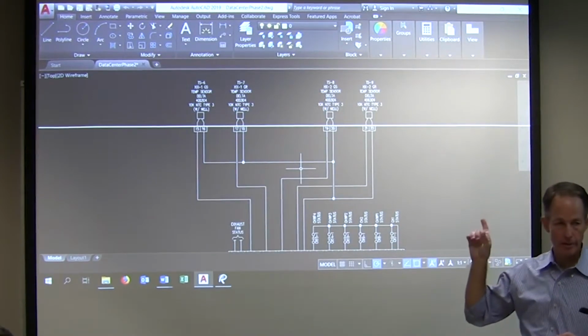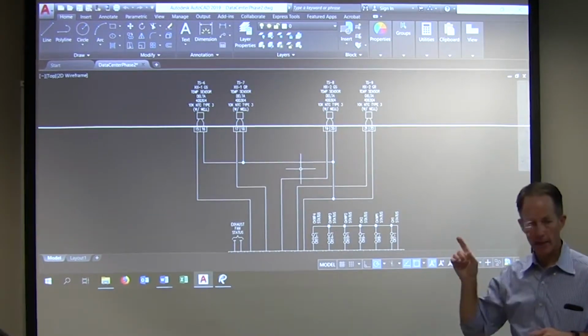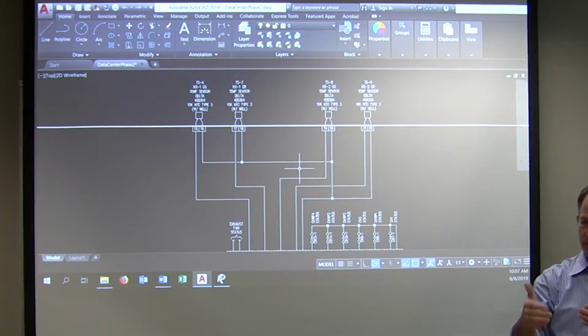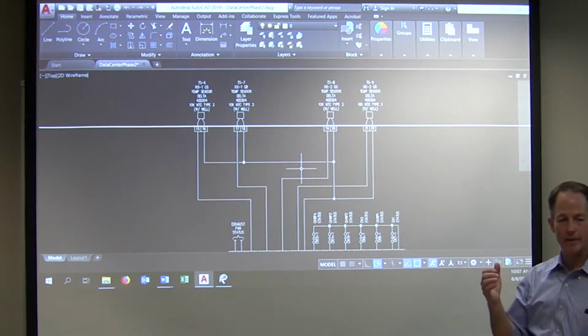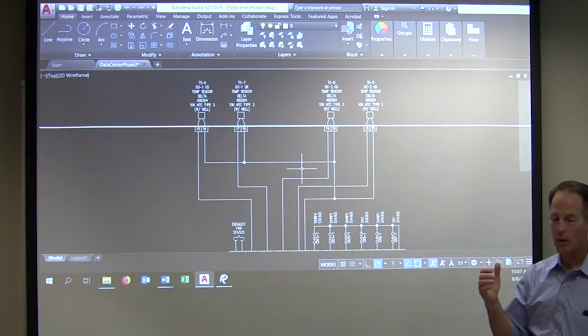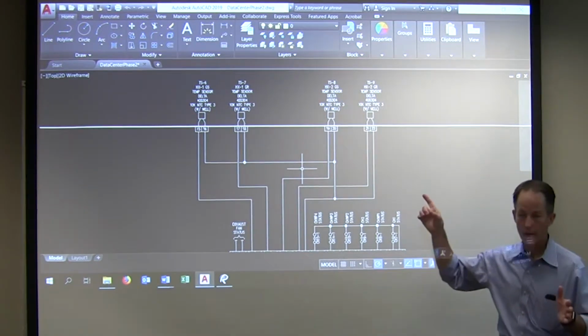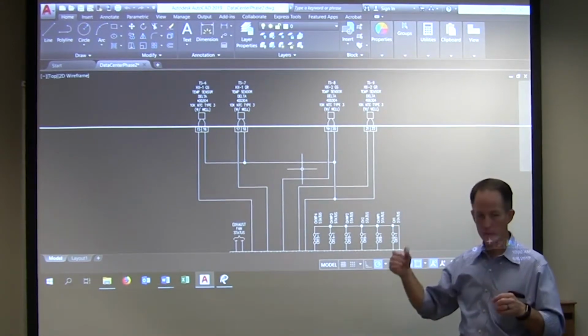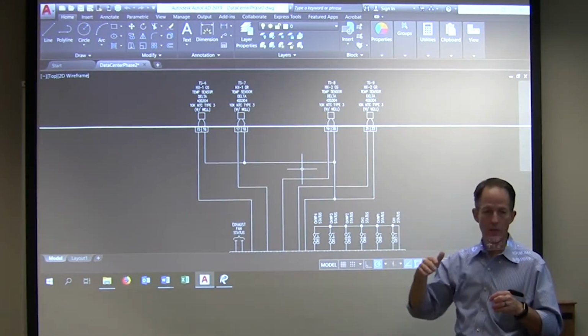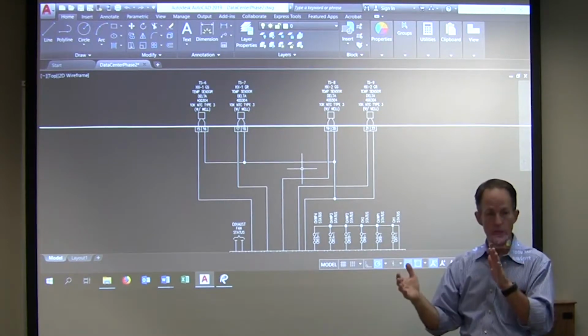We use thermistors, and again, I've got to remember if I've repeated myself in this class or the last class. Why do we use thermistors over RTDs? Cheaper. Because when that gets broken off the wall right there, it's going to cost. So cost is the big driver. As we looked at that little curve, they're pretty accurate in the ranges we need.